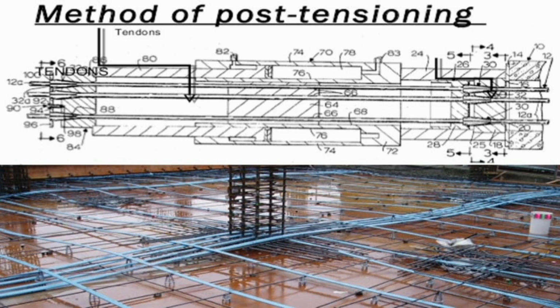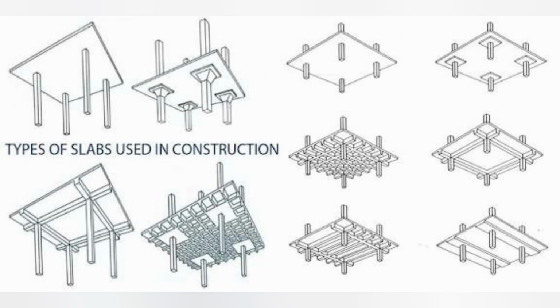Your role as a designer or builder is to understand the strengths and limitations of each system. You must ask the right questions. What are the span requirements? What is the required floor-to-floor height? What are the live loads? What is the construction schedule and budget? The answer to these questions will point you directly to the most appropriate slab type for your project.